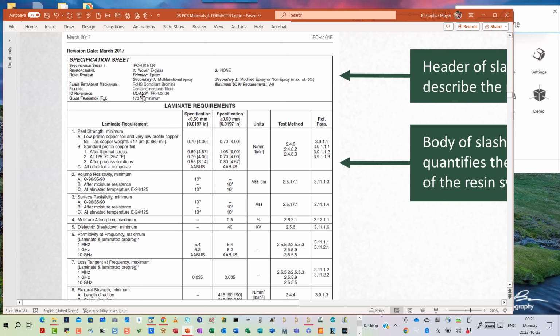And again, under UL and ANSI, it was called FR 4.0, but still /126. So yes, in the alternate specification world of ANSI UL, it had that rating system. But if you just say FR4, it's like saying, I want an IPC 4101 material. And as we'll see here, if not today, we'll see on Wednesday, there are many, many different formulations to this material. It will also be a 170 degree C minimum Tg, and it will be a UL 94 V0 rating.